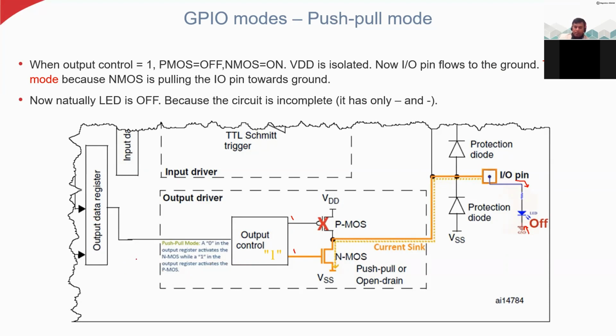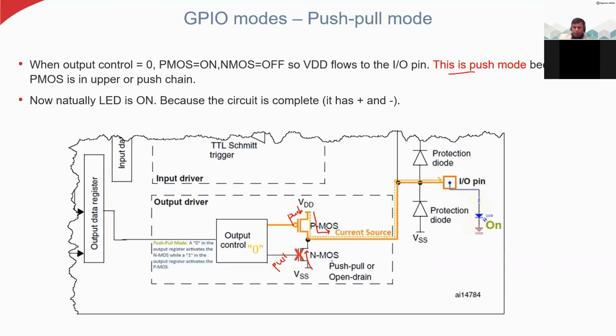Of course you can set up some kind of time delay here. Every few seconds you can give this one, and you can set the time delay and you will see the LED blinking. For example, if I set the time delay to every 3 seconds, I am enabling this 0. Then this 0 will turn on this PMOS every 3 seconds because I set the counter, and then this LED will be blinking every 3 seconds.